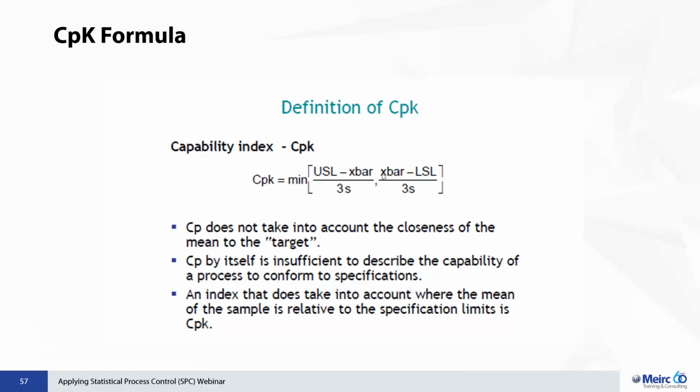then the average X bar minus the lower specification limit divided by 3 times the standard deviation. So you've got 2 values. You've got this value and you've got this value. The data is given because you have collected data about the sample, the process you're investigating, and then you have the average from the data itself.